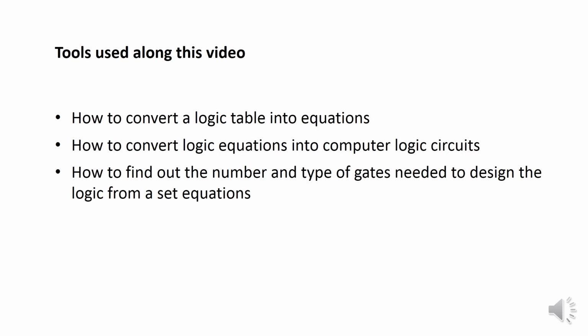I hope that on the way along this video you learn how to convert the logic table into equations, how to convert logic equations into computer logic circuits, and how to find out the number and type of gates needed to design the logic from a set of equations.